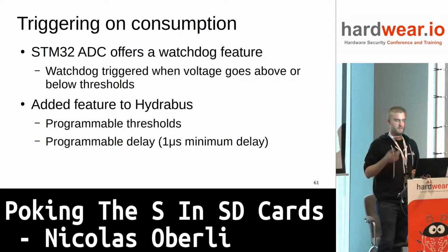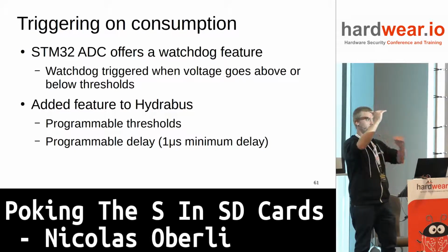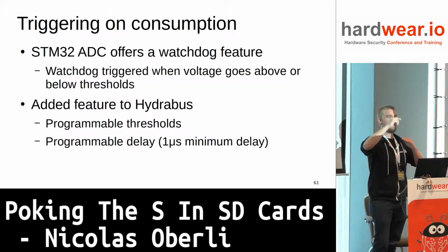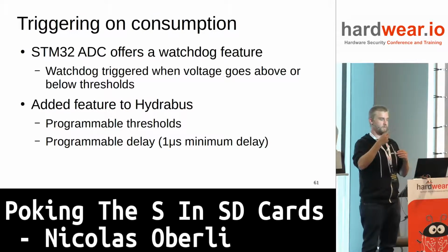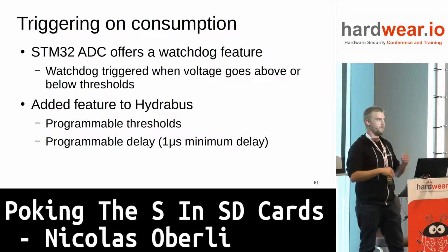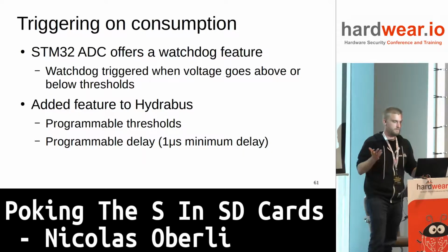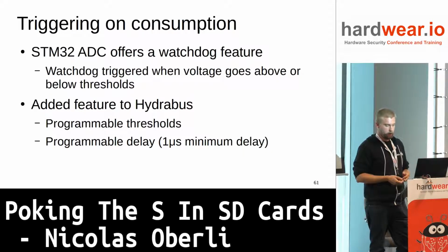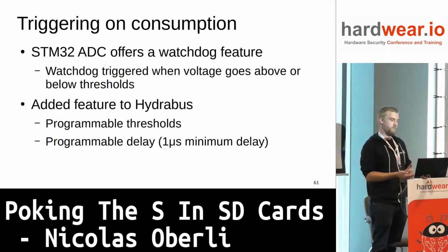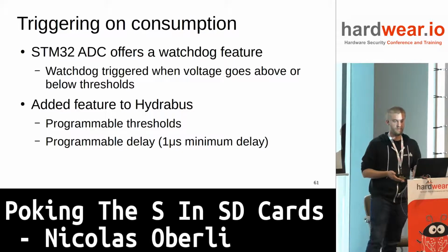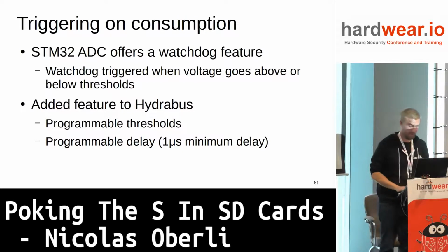In the STM32, there's a feature called the watchdog, where basically you can set a lower and upper boundary. And if the value read from the ADC goes above or below those thresholds, it will trigger some feature. So fortunately, the STM32 is the main component of the Hydra bus. Told you it was a good tool.